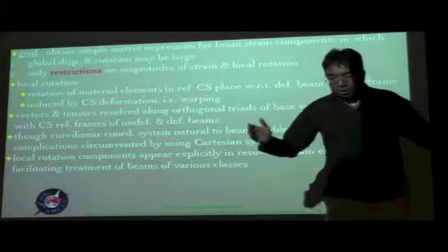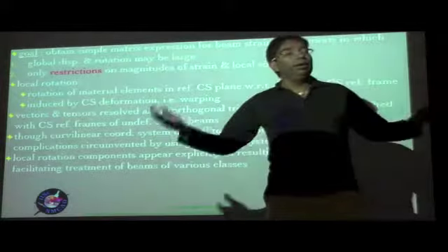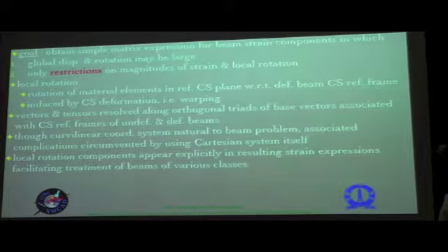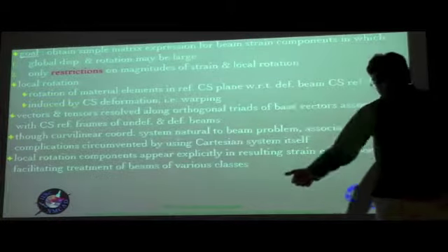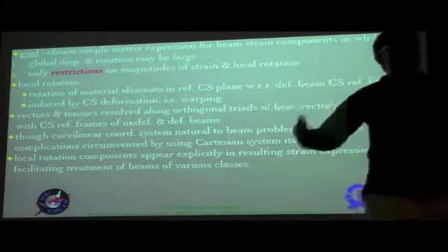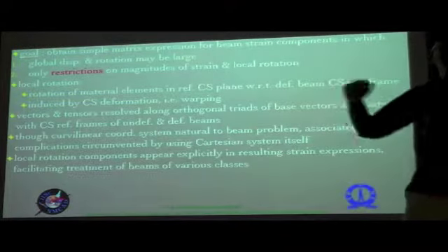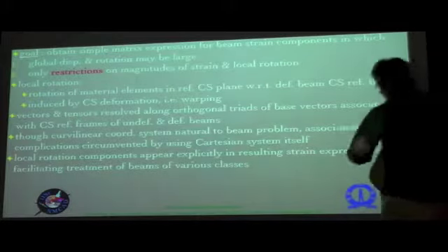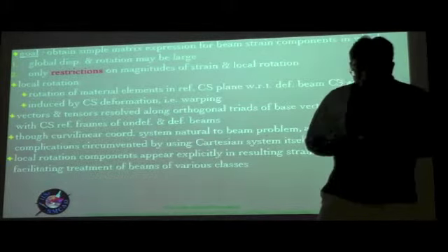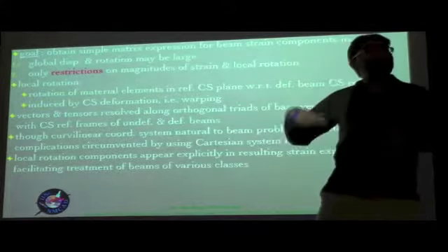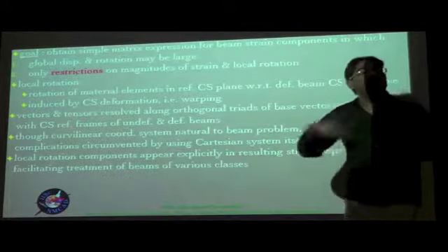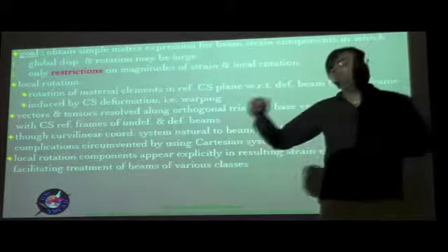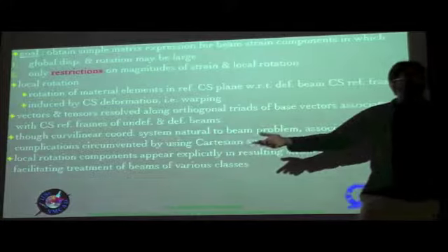We will start off in a general sense to derive the overall beam theory, especially the beam kinematics as we are talking about here, and eventually we'll express the strains, the 3D strains, apart from other quantities in terms of the local rotations as well. And when we do that, we can show by the very expressions that the local rotations will be larger in the case of S-class and T-class beams, whereas it will be much smaller in the case of R-class beams.